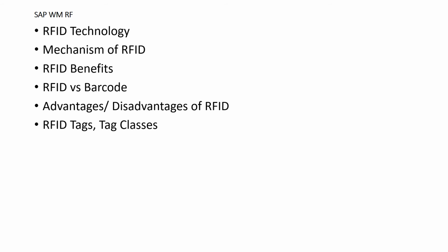So now we are seeing the class 3 read-write with onboard sensors. These tags contain onboard sensors for recording parameters such as temperature, pressure, and motion, which can be recorded by writing into the tag's memory. Because sensor readings must be taken in the absence of the reader, the tags are either semi-passive or active. This can be used well for industrial uses, to monitor pressure, temperature, and motion, everything, right?